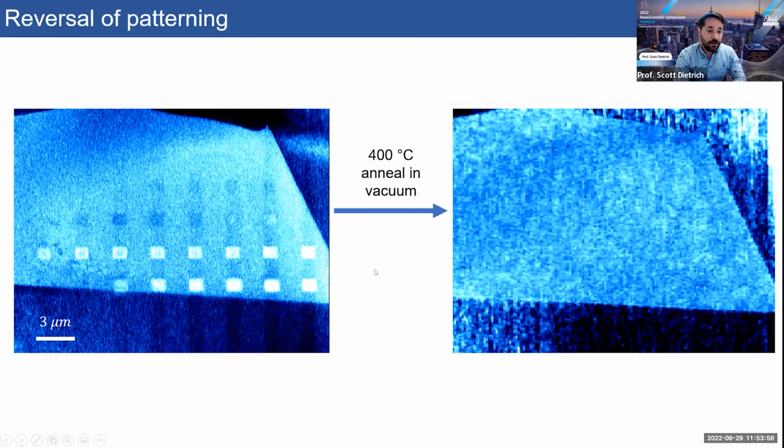A lot of fabrication techniques for creating van der Waals heterostructures and patterning them into Hall bars incorporate annealing resists at like 180 degrees C. So we wanted to make sure this process would withstand that heating. And we've shown that up to about 300 C, the features will remain on these flakes, shown in the work function here. But annealing at 400 C will kind of wipe clean your slate.